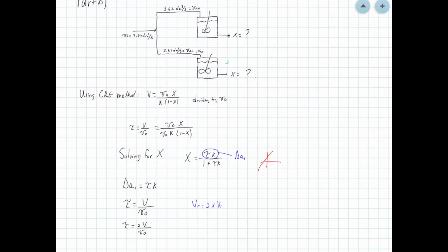The other thing that I want you to look at is that when we talk about the volume in this tau expression, we're talking about a total volume. However, because we are talking about a split system with equal volume, we have two reactors with 800 gallons, we can say that the total volume that is actually containing the reaction with that initial flow rate coming in can be calculated as a really big reactor, whose volume is double the volume of one single reactor in this parallel system.